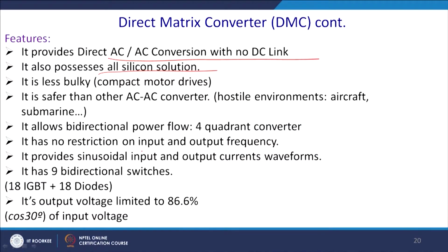It allows bidirectional power flow also. If you have a regenerative operation, you can always do that, because all the switches are bidirectional, so all 4 quadrant operation is possible. It has no restrictions on input and output frequencies.